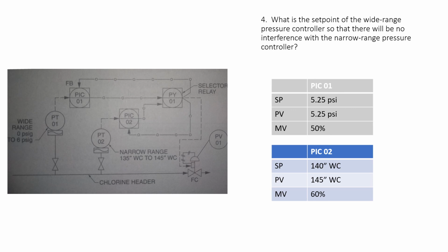So the set point of this should be 5.25 psi for number 4. It's going to go all the way up and get above its target, right above the 145, and that way the valve is open, releasing material out, and then we are controlling down from that 145 and letting it bleed back down into that 140 range. We give it a little bit of overshoot when we're purging it with air, and then as that electrolyzer comes up, it's going to be working.